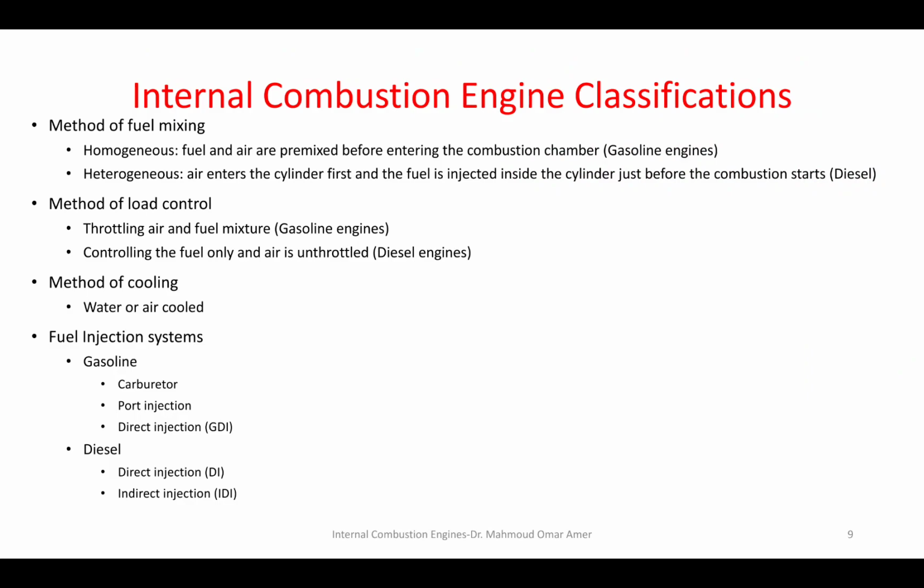So do diesel engines operate at constant lambda value? No. At very low loads, the amount of air is the same, and very small diesel fuel amount. So the air-to-fuel ratio is very high. As you depress the accelerator pedal and the amount of fuel increases, the air-to-fuel ratio decreases. But overall, in diesel engines, the operating condition of the mixture is always lean combustion. Even at maximum loads where the maximum of fuel is injected, it's still lean combustion. Okay? Why is that?